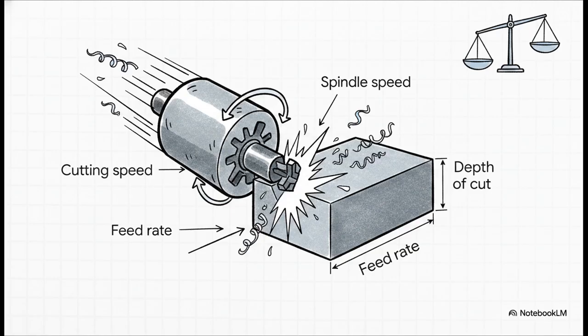As technical students, you'll quickly learn that machining isn't just about forcing a tool through metal, it's about balance. If you feed the tool too fast, it snaps. If you spin the spindle too slow, you get a terrible, rough finish on your bracket. Balancing these parameters is how we ensure both machining efficiency, so the job gets done quickly, and top-tier high quality for our final physical bracket.